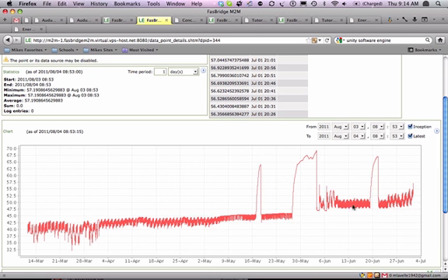Another interruption of power, and as the summer goes on and we're into the cooling season, we're pushing heat from the buildings back into the ground well field. And at this point, it's hitting the well field at about 50 degrees. Gives you an interesting idea about how the building is performing, what the temperatures are doing over a period of time. Notice there's some raggedness down here in the left corner, and this is when the compressors are being tuned up for the control algorithm.